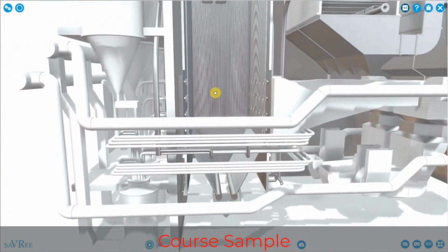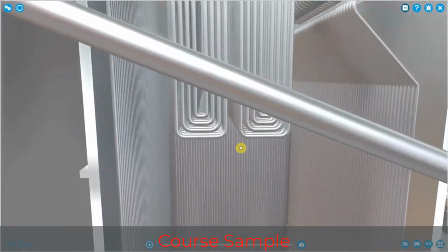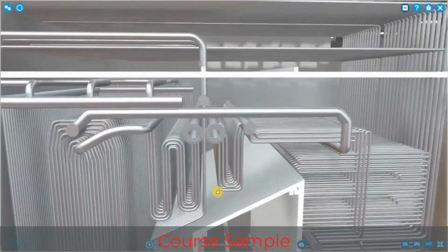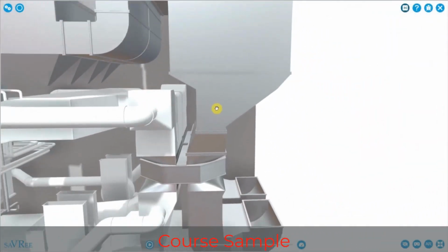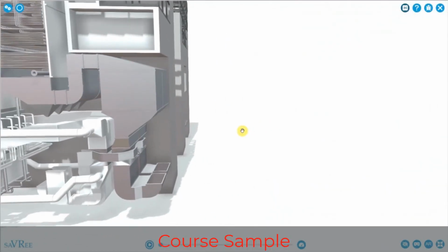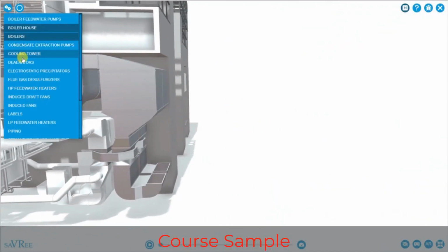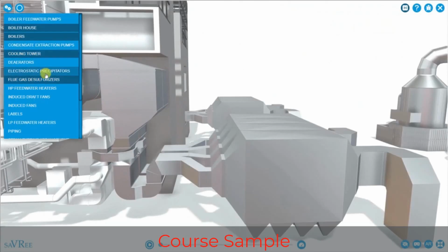When we get combustion, the exhaust gases are going to rise up here, flow through the boiler, across all of these tubes, down here, along here, and then we're going to go into our flue gas cleaning system, also known as our exhaust gas cleaning system.